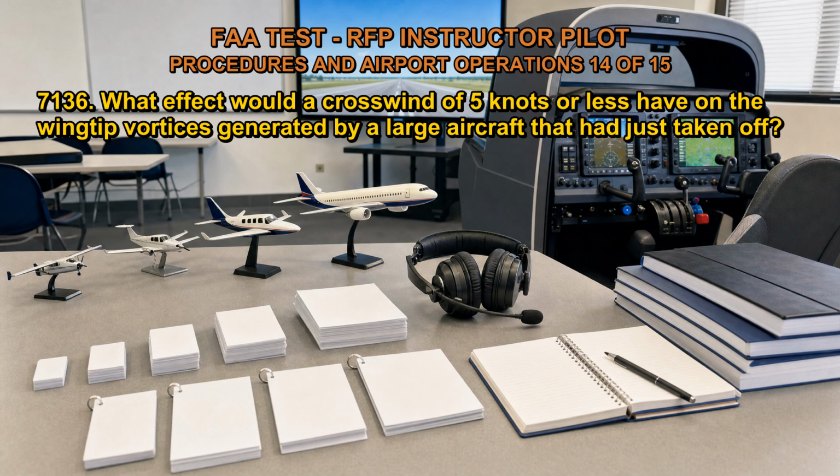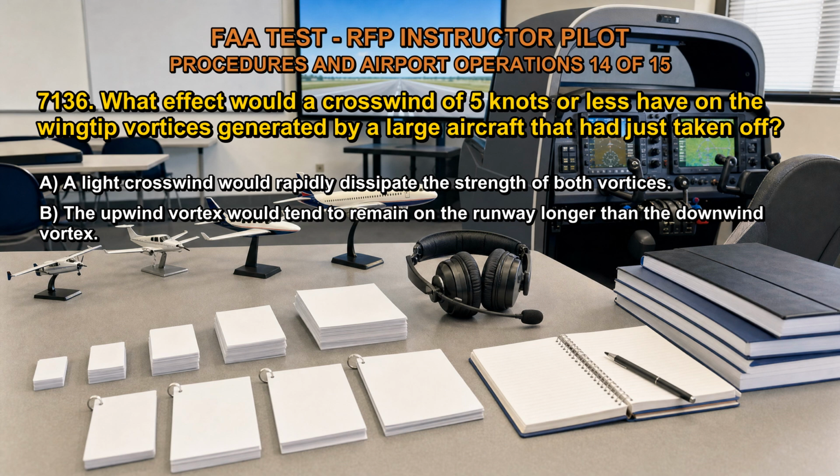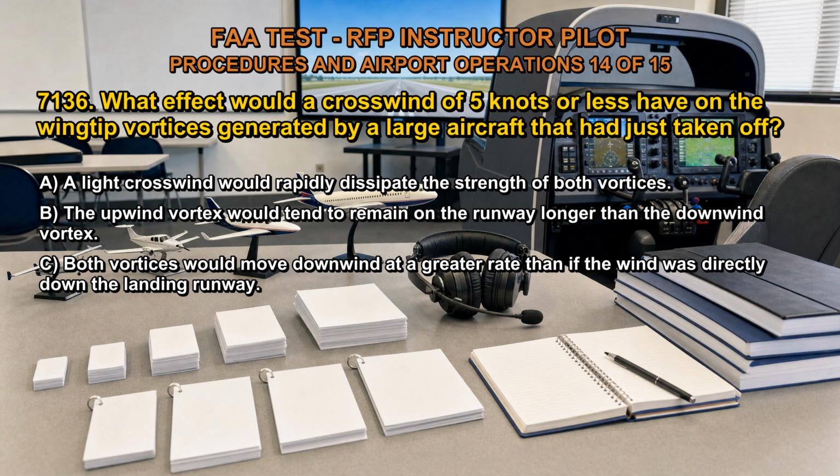7136. What effect would a crosswind of 5 knots or less have on the wingtip vortices generated by a large aircraft that had just taken off? A. A light crosswind would rapidly dissipate the strength of both vortices. B. The upwind vortex would tend to remain on the runway longer than the downwind vortex. C. Both vortices would move downwind at a greater rate than if the wind was directly down the landing runway.